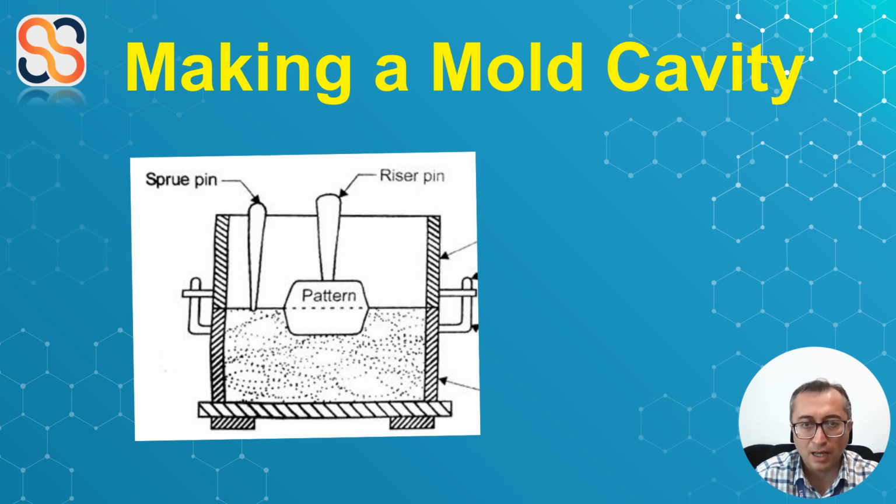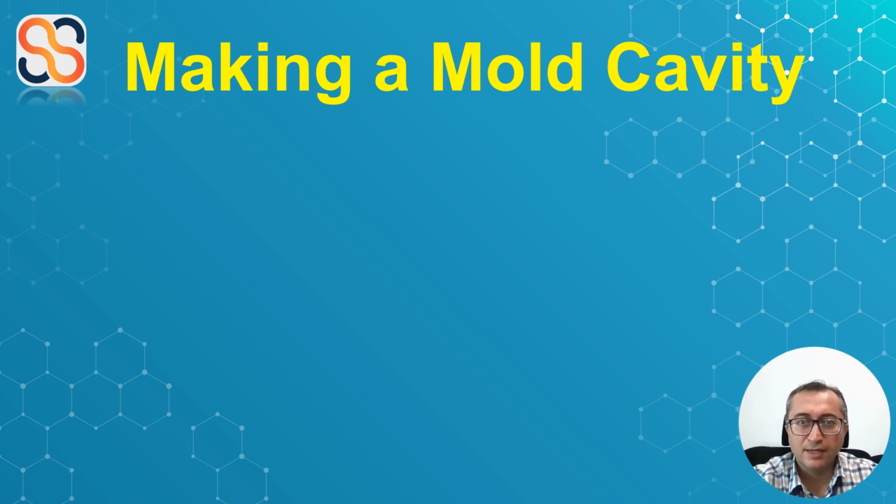Once that is done, we sprinkle parting sand over the top of the cope surface and roll it back onto the bottom board. We then carefully rap and remove both the cope and drag patterns. If needed, we make any repairs to the mold and apply dressing to smooth it out. Finally, we cut the gate connecting the lower base of the sprue basin with the runner and the mold cavity.